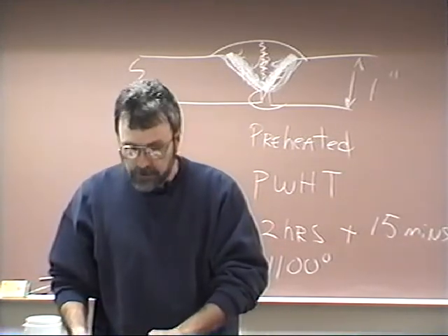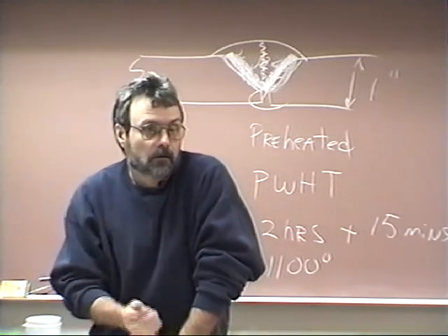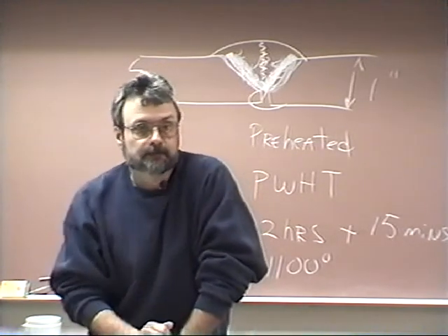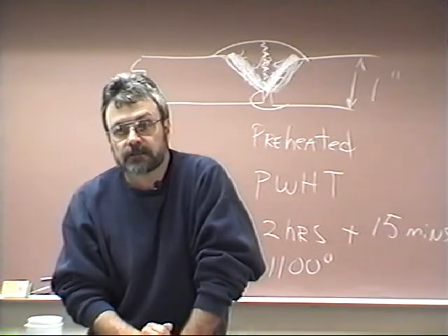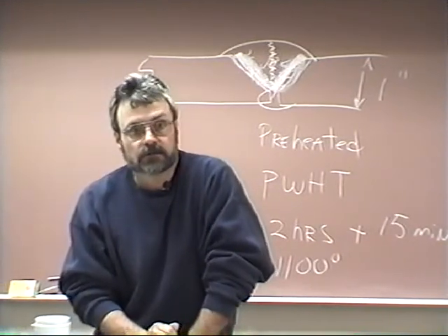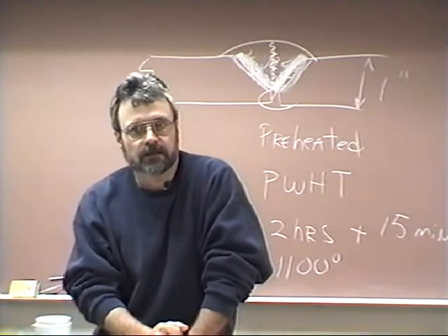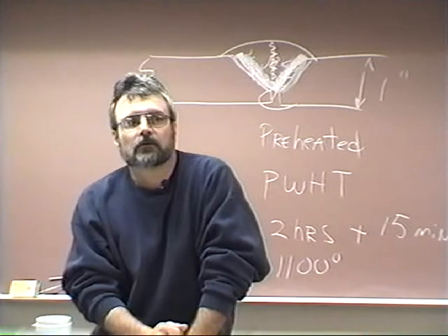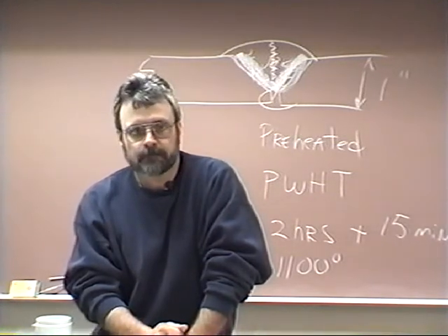And also, depending on the criticality of it, when we do finally make a repair, we might put the root pass in and then X-ray it or PT it, dye penetrate it, to make sure that everything's out. Then we may have to do some additional grinding. And the most important thing is make sure you don't have to go back into it again. I think a typical rule of thumb is you can repair something twice, and the third time you've got to cut it out and replace it.